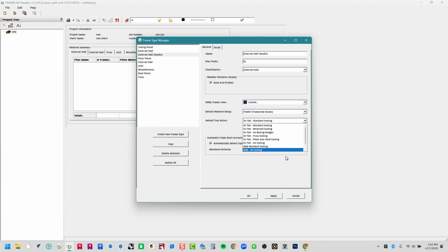Back to back, B to B. The webs of the plates are screwed to the webs of the studs. The lips from the plate are furthest away from you when looking in the elevation view, while the lips of the studs are closest to you. You should be able to look at the drawing to tell; this is the lip lines and are shown on the stud members. Truss chords are referred to as plates and truss webs are referred to as studs.